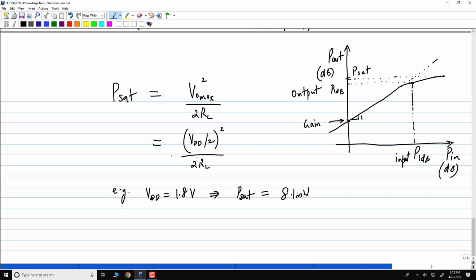Yes. If we give a sinusoidal input, the output won't be sinusoidal. It will be square. If it's a square wave, then there should be a factor of 4.5. Yes, there could be, if you drive it really hard such that it becomes a square wave. Normally the RC bandwidth will never allow you to get a square wave at the output. You'll never get anywhere close to that. Second thing, what you're saying is correct. Normally you will have to put in a filter to remove all those additional harmonics. All those things I'm not showing, but you're absolutely right.